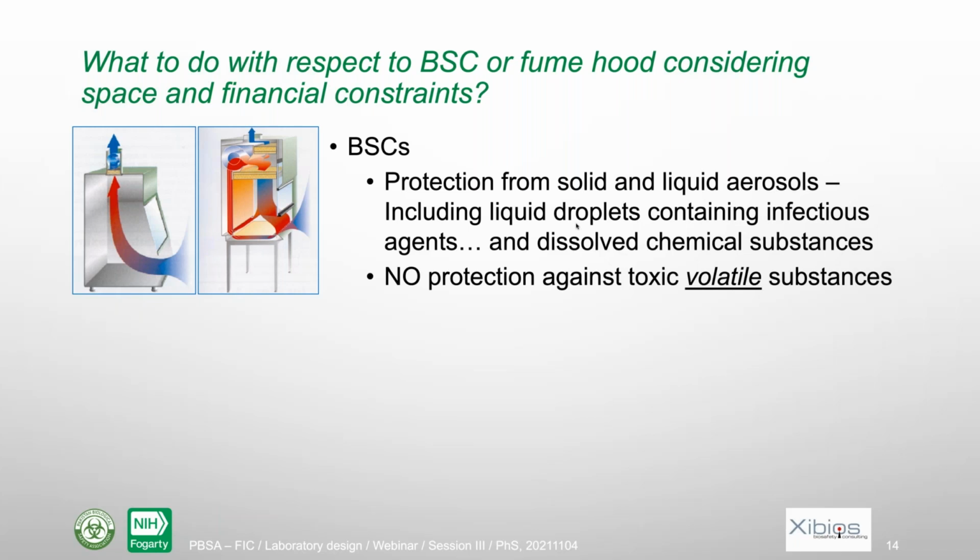Biosafety cabinets are made to protect people from solid and liquid aerosols. It's mainly liquid aerosols because we mainly deal with liquids in biological labs. And so the filters will trap those droplets that may contain biological agents, but also dissolved chemical substances. So chemicals which are dissolved in your liquids will also be stopped by the filter. On the other hand, if your toxic substances are volatile, if they are in the air and not in droplets, in that case, they will pass through the filter, and so you could be exposed.